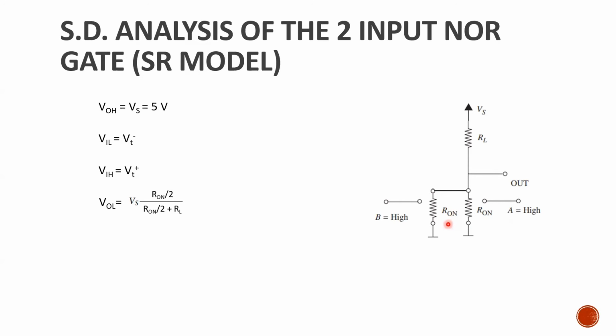So guys, a very important interview question on VLSI fundamentals and PD concepts: in which universal gate is the noise margin high? Means with respect to the noise margin, which device is better? None other than the NOR gate only, because the VOL is less, but in the NAND gate the VOL is somewhat high.